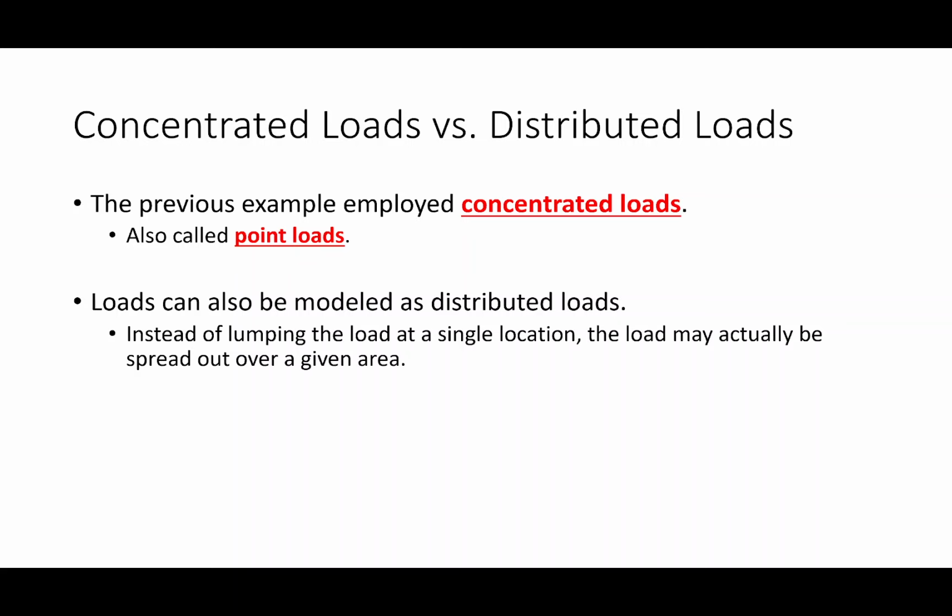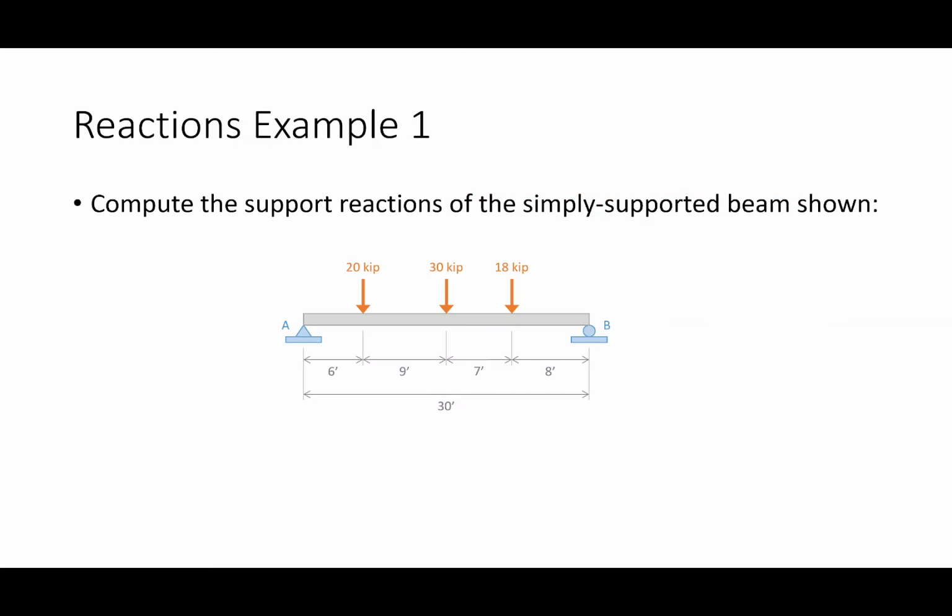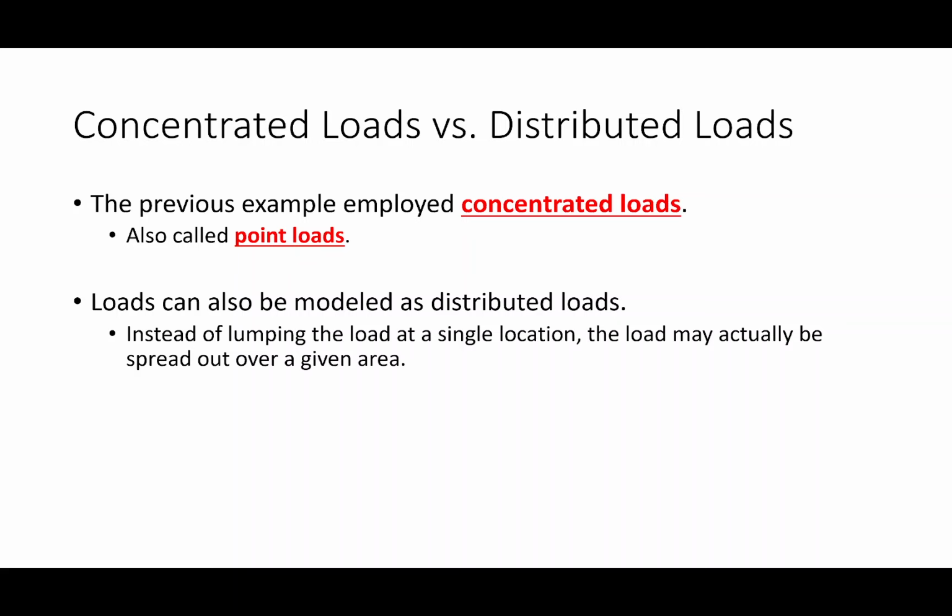What we just did in this past problem, these are concentrated forces. This is a 20,000 pound load that is just right there at a single point. Do we deal with that type of effect in the real world? Yes, we do. Like a common place where we would see that is if we have beams connecting into girders, and those girders have to support the end weight of those beams all at that point of connection. So yes, we do experience, utilize concentrated loads. If you ever hear me use the term point load, that's what I'm talking about as a concentrated force.